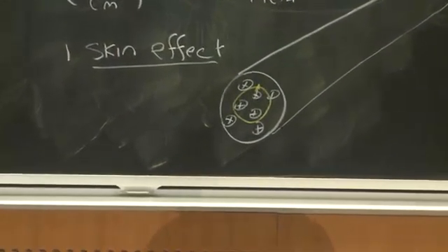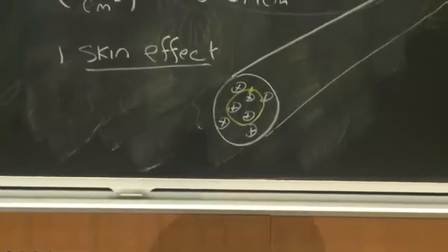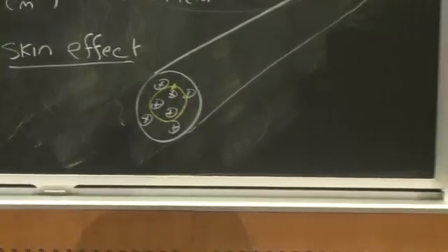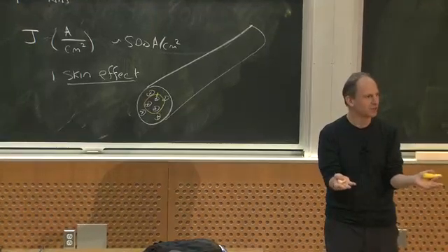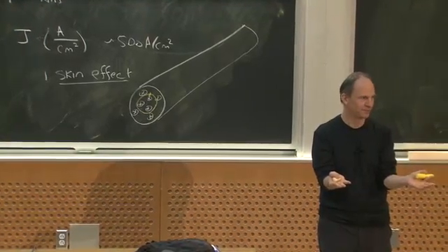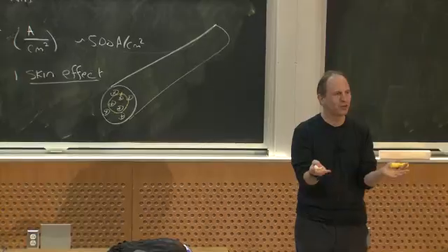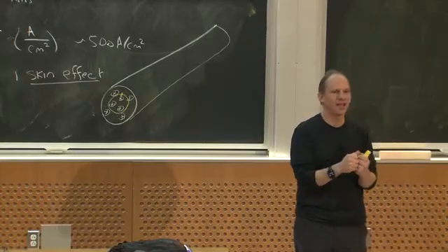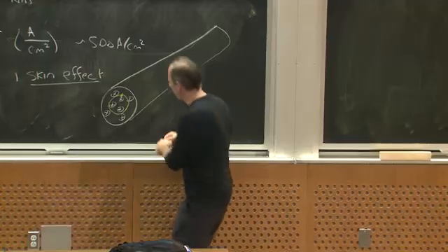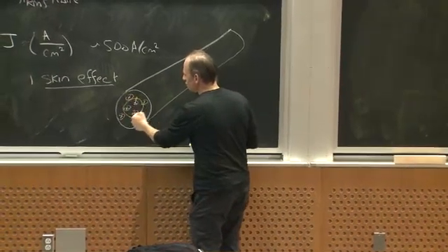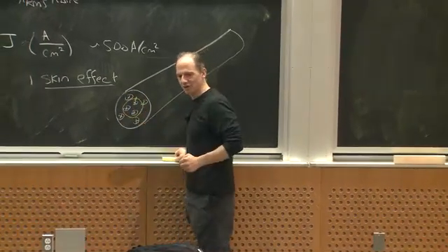But what do we know about something that generates a dB/dt, a change in magnetic flux density? We know by Faraday's law that generates a voltage, and that voltage is going to cause, essentially, eddy currents to circulate within the wire. They're going to try to reject the change in magnetic flux density in the wire.